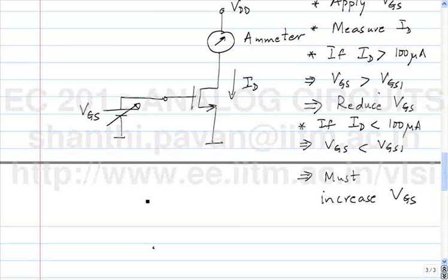Does this make sense? So in other words, you are comparing the drain current of a transistor, ID, to some reference current, IREF, and you use the error. Whenever you compare, what are you doing mathematically? Bill Gates has got so many millions, your roommate has got whatever, multiplied by 10 power minus 9. When you compare, equivalently it is subtraction between the two of them. So comparison, even though you're not used to thinking about it in mathematical terms, is basically subtraction. So you compare the output ID with the reference and use the difference, IREF minus ID, to control the animal, which is the transistor, and the knob you use to control the transistor is VGS1. You understand?